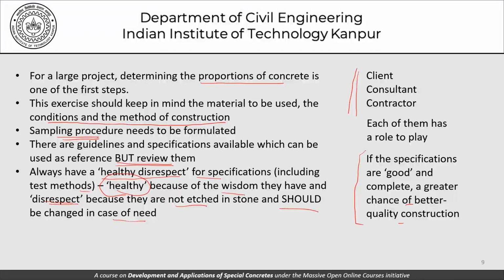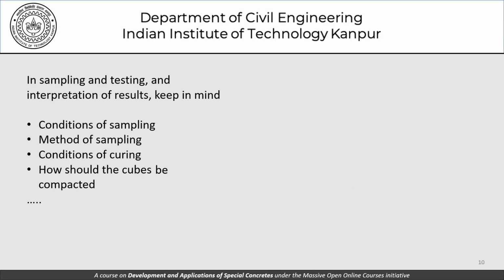If we jump into those projects, start those projects with inadequate preparation, it is more likely to run into trouble than otherwise. In sampling and testing and interpretation of test results, keep in mind the conditions of sampling, method of sampling, curing conditions, how should the cubes be compacted. I mean, these are the kind of things which are very, very mundane, which are very, very obvious.